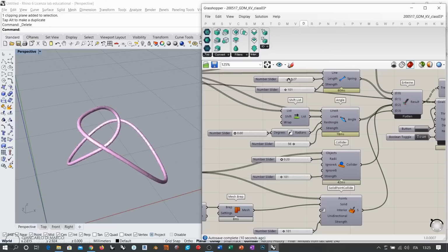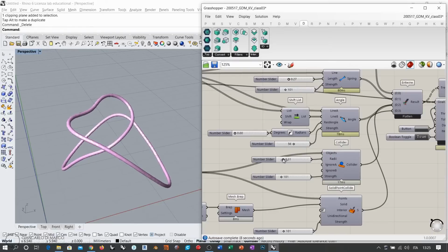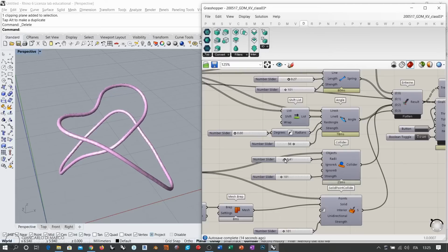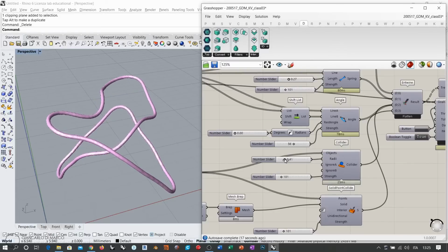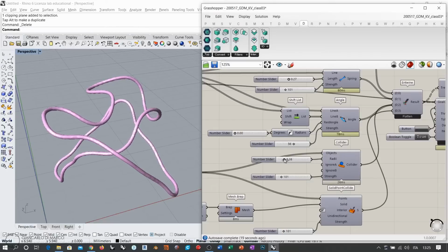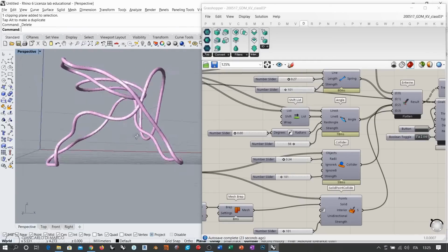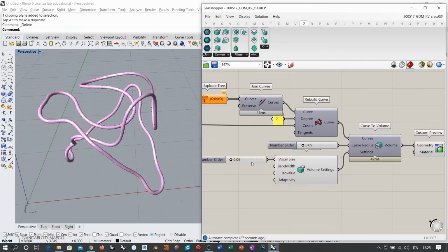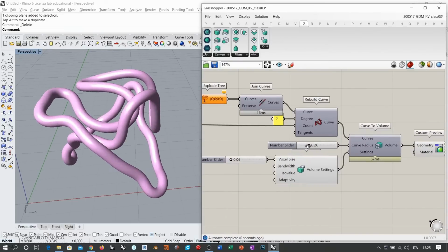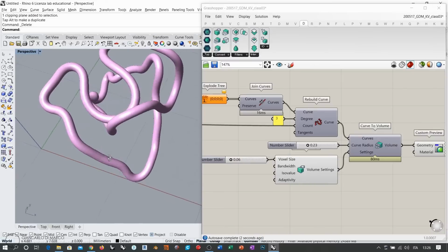So this curve will tend to expand sooner or later, and if it doesn't, you can simply increase the collision angle and then decrease it. When you see that the curve starts to expand, you decrease the collision angle in order for this deformation to happen slowly, like this. And once you have reached the desired result, let's say that this is the desired result, then you have the possibility to play around with this shape as much as you please.